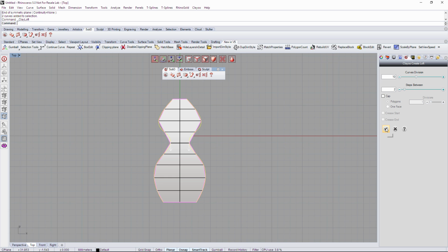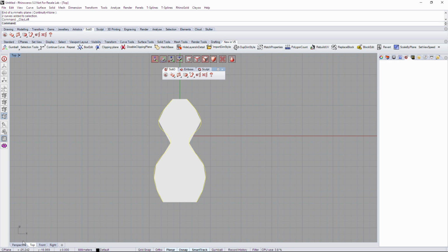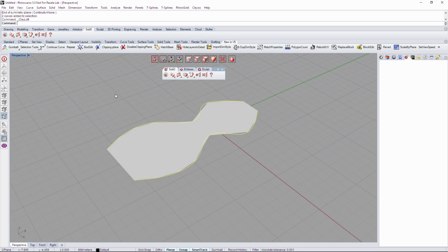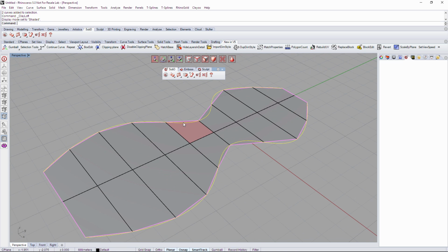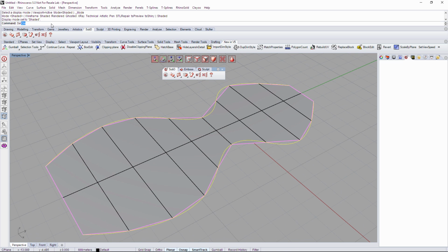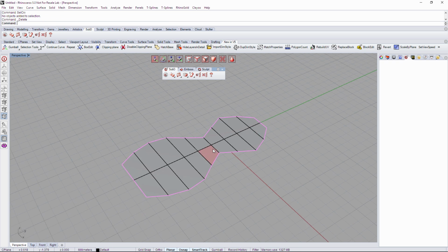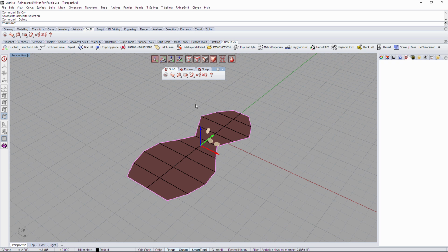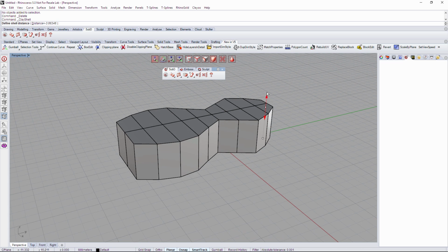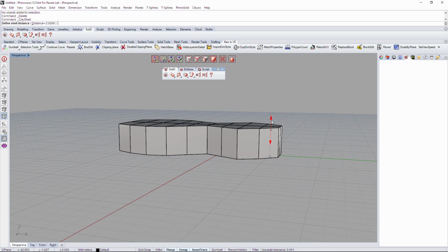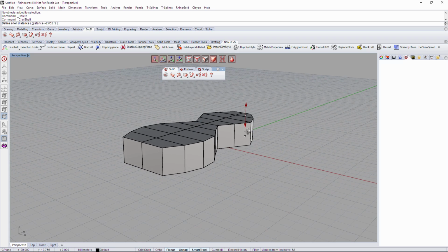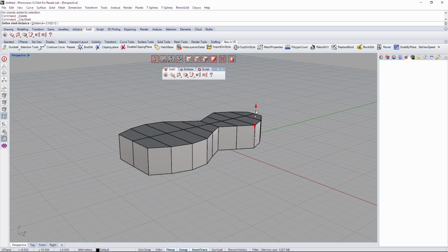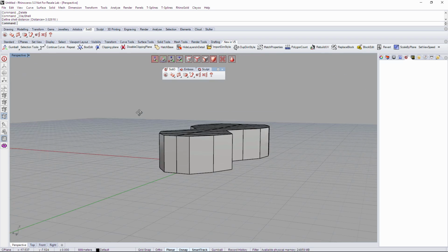So right now I'm just going to validate that. Okay, and here I have my geometry just in plane. So I'm going to use the display mode shaded. I'm going to go to select curves, and I'm going to delete the curves that I've used to create the body. Right now what I'm going to do is just extrude that, so create extrusion with a common shell, just to make sure that this is a 3D geometry, not only a surface. Okay, and I'm going to validate.